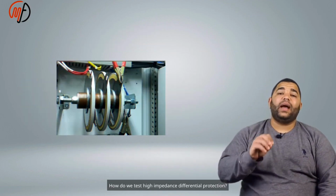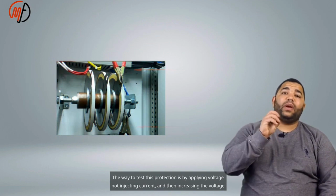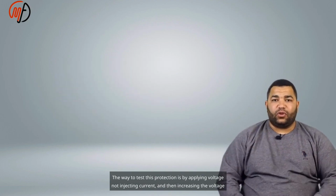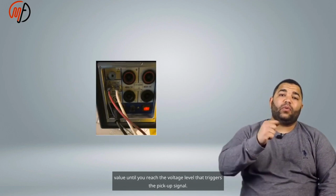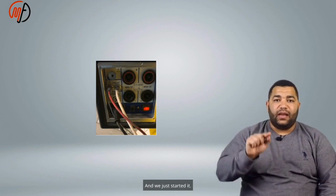How do we test high impedance differential protection? The way to test this protection is by applying voltage, not injecting current, and then increasing the voltage value until you reach the voltage level that triggers the pickup signal. And we just started it.